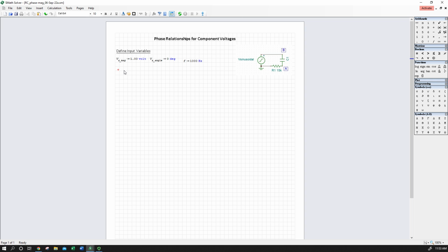Okay, so what else do we need to define about our circuit? Well, how about the values of the capacitor and the resistor? So again, we'll define those the same way. Colon, we'll go C for capacitor. And let's just put a starting number in of maybe 1 microfarad. So we do micro by saying we have 1 as our significant value times 10, and we use the up caret to denote an exponent, and then -6.